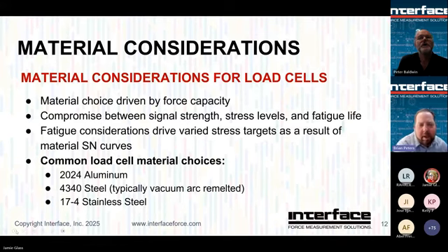So it's a balance. We can certainly make a load cell that provides a great signal and may not last very long, or we can provide a very low signal load cell that will tolerate nearly any force you can throw at it. But it all comes down to managing stress targets, specifically relative to the material's SN curves.